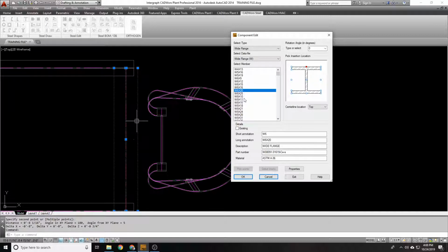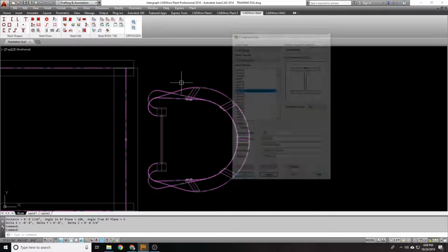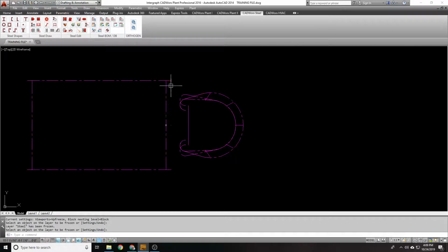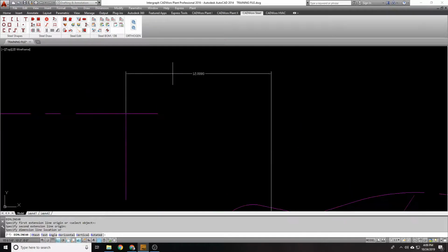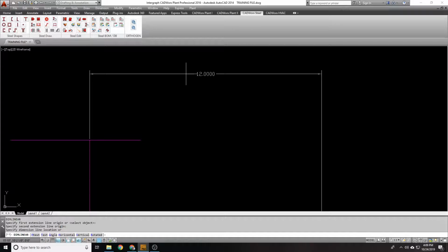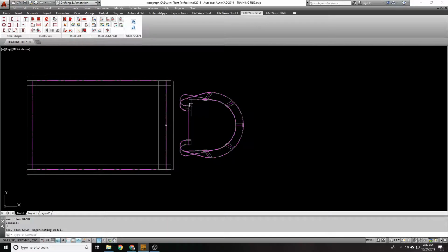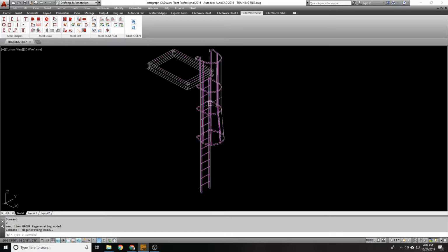And it seems like more work than it is to just put it on the edge. But what happens is when you dimension in single line, you're only dimensioning to your center lines. So it looks kind of like this, right? When you dimension in single line steel. And so to dimension to the outside edge of the steel is difficult unless you're showing symbols. Then maybe you can do it. And even then it gets kind of messy. So what I like to do is give that dimension, you know, here to whatever that is. And in this case, with my decimal unit set up, it's showing 12 inches exactly. You get a nice round number, and you're going to the center line in your single line steel. So that's why I choose to do that. But, you know, use it at your own discretion.